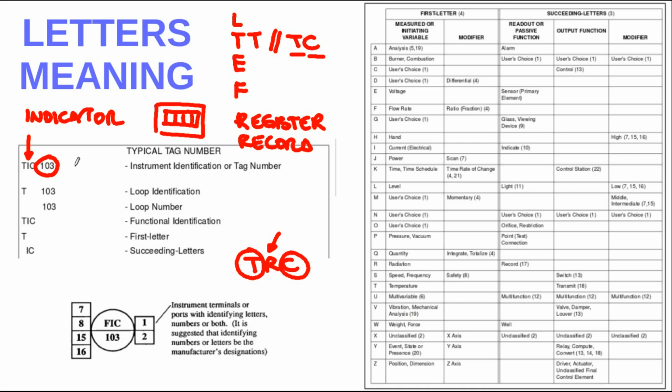We can have in a diagram different temperature controllers, but these temperatures may not have anything in common. So then we may have, for example, TIC 102, for example, TIC 103. These are both temperature controllers, but their temperatures have nothing in common. They belong to different control strategies, control loops.